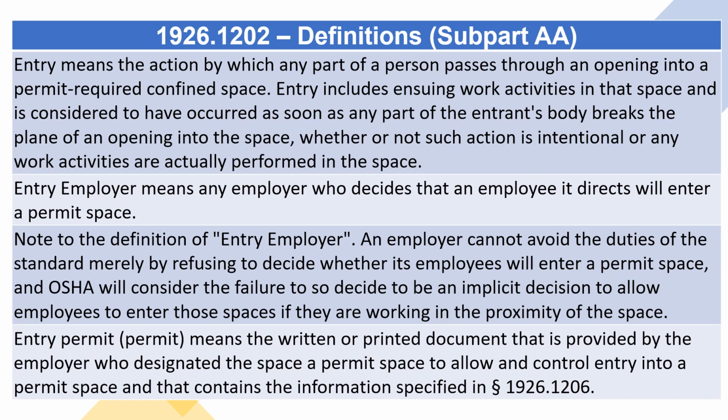Entry means the action by which any part of a person passes through an opening into a permit-required confined space. Entry includes ensuing work activities in that space and is considered to have occurred as soon as any part of the entrant's body breaks the plane of an opening into the space, whether or not such action is intentional or any work activities are actually performed in the space. Entry employer means any employer who decides that an employee it directs will enter a permit space.